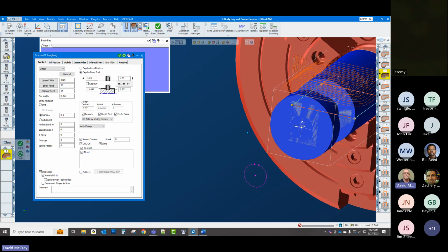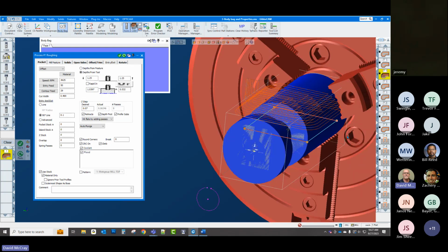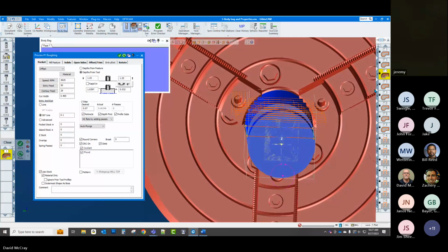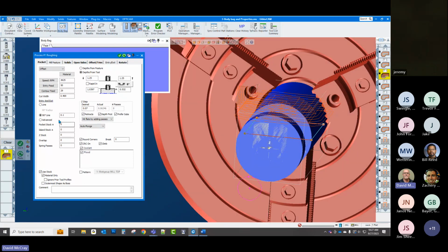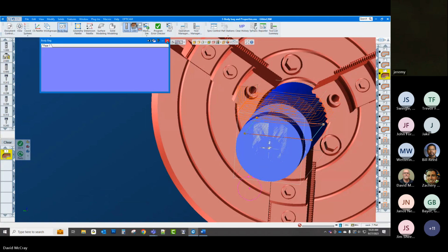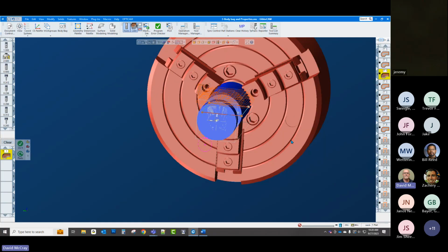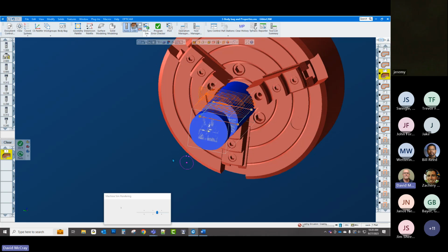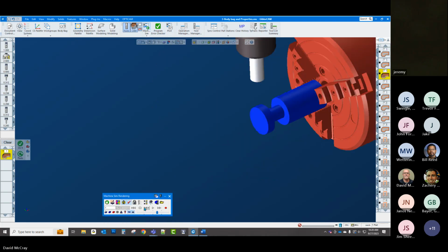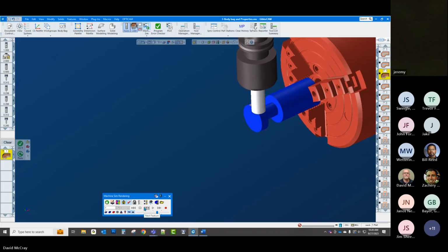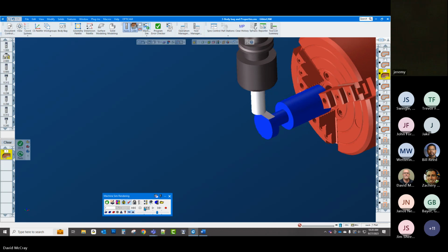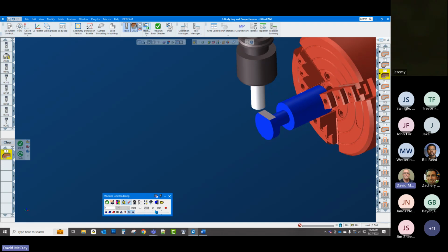What's there? Same thing with this. I'm using 2D geometry to drive the toolpath on this. But if you look here, it actually is looking at where the stock is, making the cut. I've got a 100 thou entry line on it, and making only the cuts as necessary. So when I simulate this, if I single step it, you're not getting excessive toolpath.